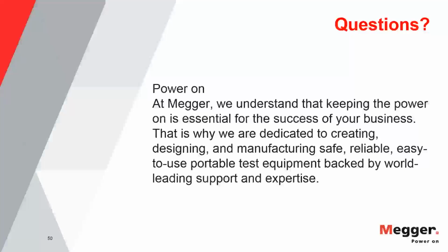So the way you do the test is much different from a pure diagnostics test, as Jason explained, with these different steps where you try to determine the different parameters, specifically the inception voltage. You apply the voltage according to the withstand table, table 3 in IEEE 400.2, but you use the PD as a trending indicator to see if there is any condition going on.